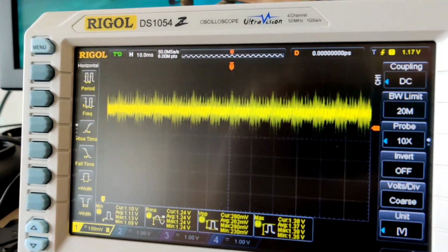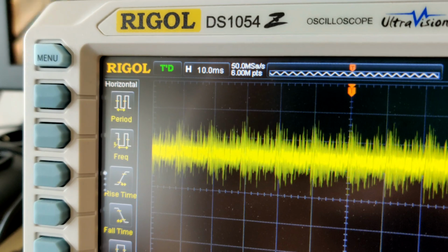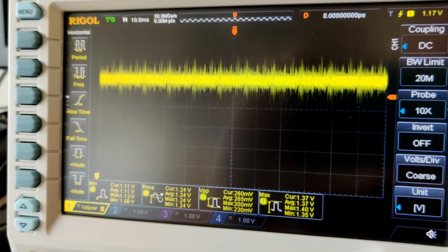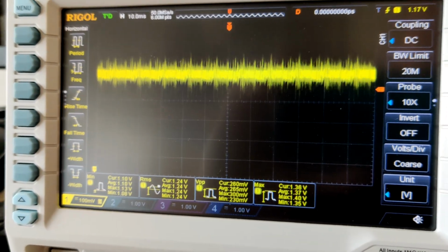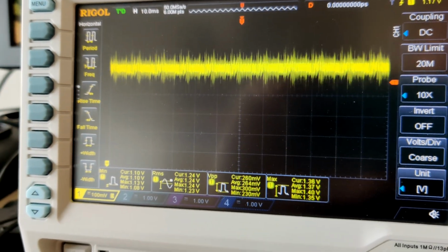So every single time something repeats, that's another frame render cycle starting or ending or doing a specific thing. And by calculating the difference between those periodic parts and then taking into account your per division time, so right now we're on a scale of 10 milliseconds per division, you can actually calculate the FPS that you're running at by looking at this, because that's just actually what we're looking at.